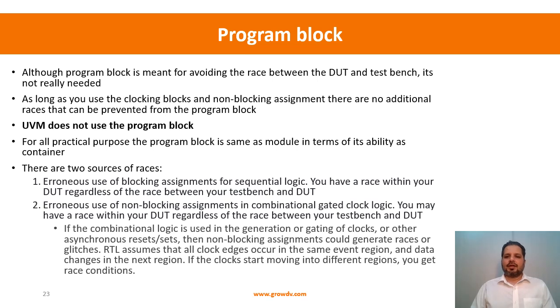So we'll briefly look into what a program block is. A program block was meant to be the container for the Testbench code. We had even used it in the context of the FIFO Testbench for completeness. The idea was that whatever code you write for the purpose of the Testbench, you put it in a program block, and it had almost equivalent capabilities as a module. Whatever a module could do, even the program block can do.